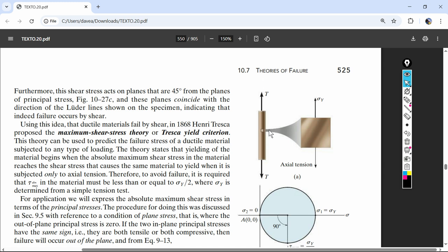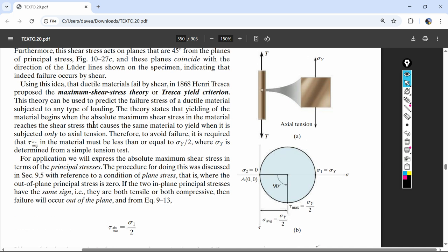And so we pull on something, we get that value. And then I still think this absolute maximum shear stress just means that we do our equations and get values for that max shear stress that we're observing. And if it's larger than this test scenario where we pull something in tension and it starts to yield at 45 degrees, then you can't pass that point. That's the point where that's yield in this case. That's failure. Yield due to failure due to yielding.